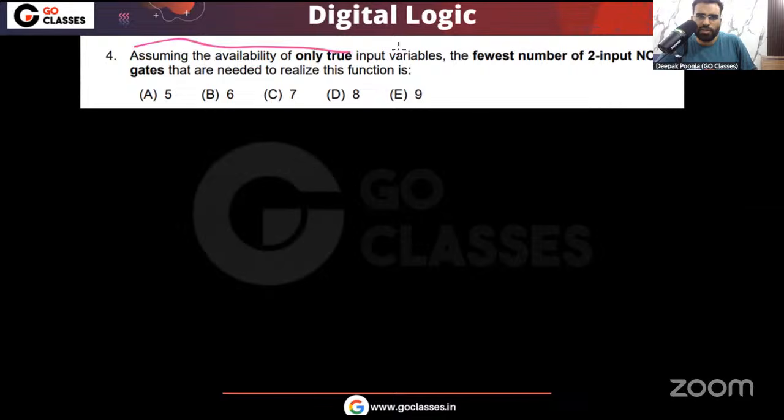Assuming the availability of only true input variables, means the complemented variables are not available to us, the minimum number of 2 input NOR gates required to realize the function. What is the function expression? The function expression is x or y bar z bar. This is the function expression. Okay, correct. Now let's see what will be the answer.